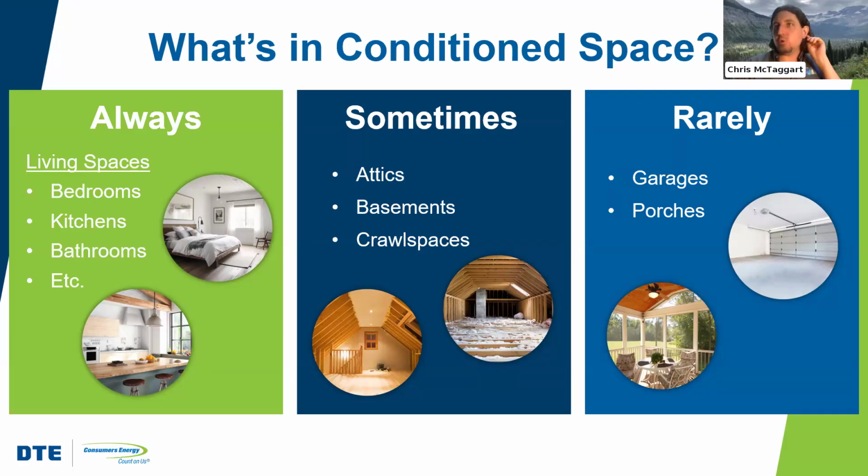Rarely are garages and porches conditioned space. Not never. Technically, by the code, garages sometimes are conditioned space. If you've got direct conditioning to them, they can be included within conditioned space by code. Now, when you start to get into HERS ratings and above code programs, generally speaking, we're not including garages within our definition of conditioned space.